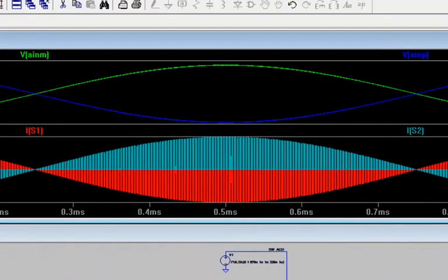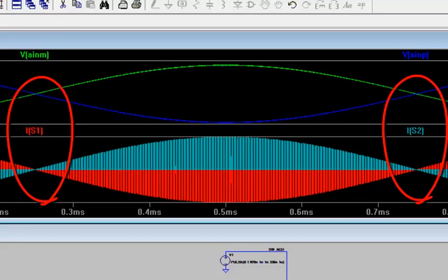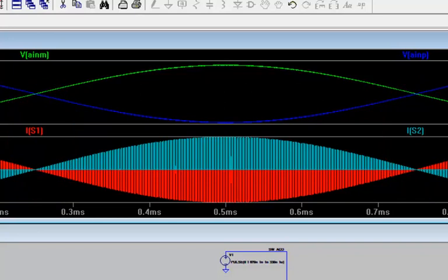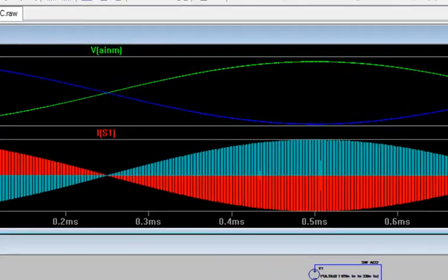Because the sample capacitors always are discharged to 0 volt before being reconnected to the inputs, and the input signal is not 0 volt, every time that the input switches get closed, there are these immediate spikes of current being drawn through the switches to charge the sample caps. What we see in this waveform is that sometimes the current spikes are 0. This is when the two inputs are equal to each other at 2.5 volt, because then there is no voltage difference between the inputs and the discharged sample capacitors.